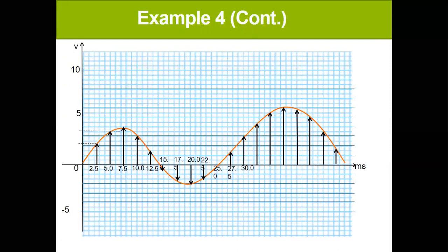Now, let us see. This is the original signal. Maximum is 5 volts. Minimum is -2 volts. Just as we discussed previously. So if our sampling rate is 400 Hertz, the sampling interval is 2.5 milliseconds. This one is in terms of milliseconds.